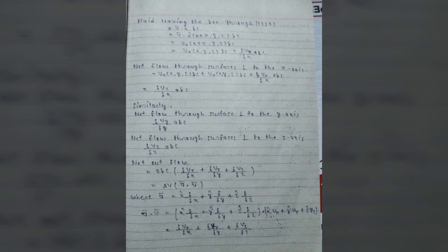Remember, the surface 5, 6, 7, 8 is at x. This is going to be x plus a, but all other points, all the points have same y and z, B, C, right? So, which I can write as Vx at x plus a, y and z, BC, which I can further write as Vx at x, y, z, BC plus partial derivative of Vx with respect to x, BC, with the result that net flow